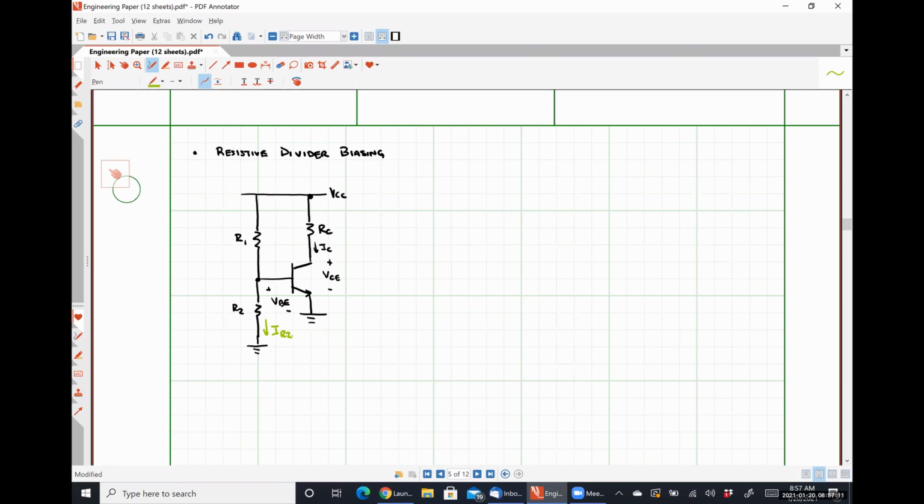So if the base current, let's call this guy IR1, is negligible, that means we are considering that the current I have labeled as IR1 is roughly the exact same thing as the current I have labeled IR2, which means that our base emitter voltage VBE is pretty trivial to figure out because it's just a simple voltage divider. We're assuming effectively that everything to the right-hand side of our voltage divider doesn't load our voltage divider and cause that output to change, all right?